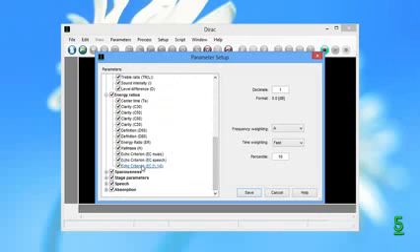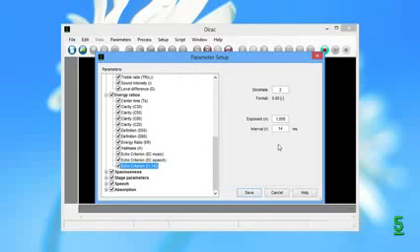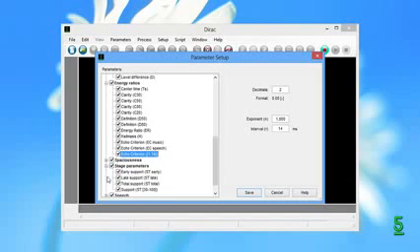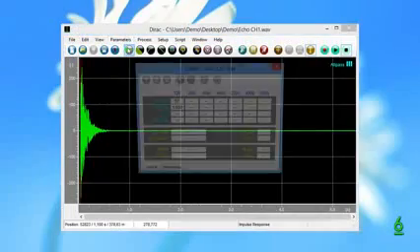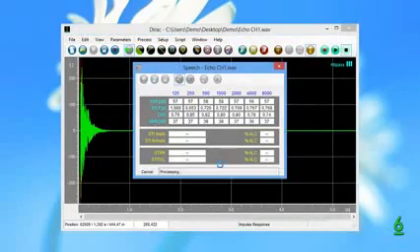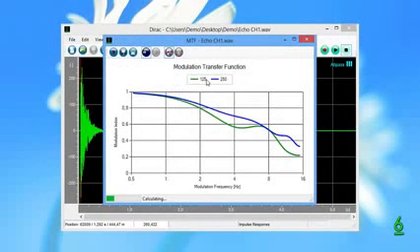Next to the predefined echo criterion parameters for speech and music, there is a configurable version, and there is now also a user-defined version of the stage support. The speech parameter window has been modified, as the parameter calculations have been updated to conform to edition 4 of the IEC standard. RASTI has been removed, but it is still available in the parameter graph window.